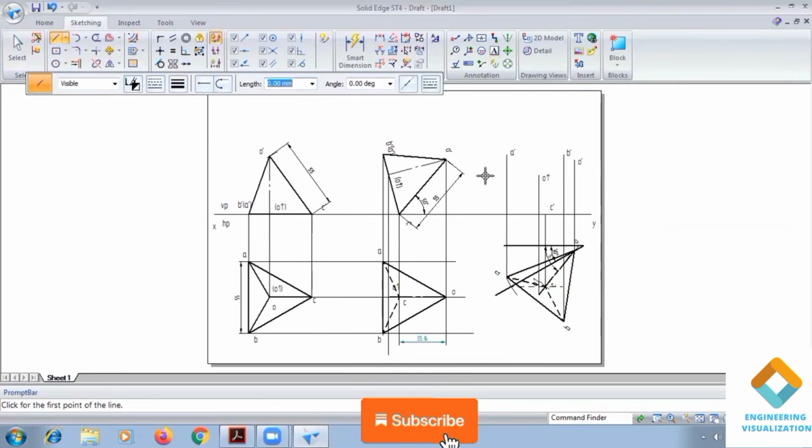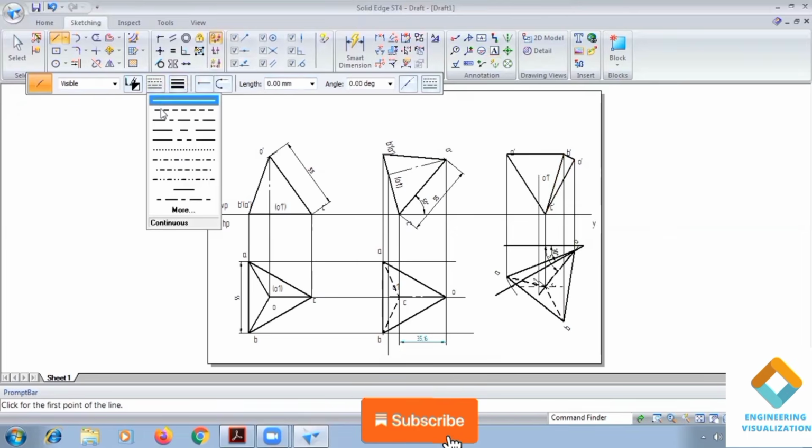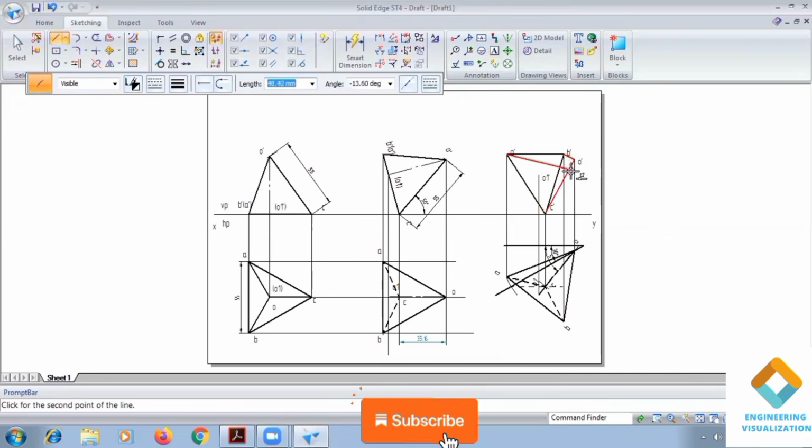Okay, after writing the notations, you can join it first. Join the triangular face and then the slant edges. If any of the slant edges pass inside, that will be a dashed line. Passing outside means it is a continuous one. So the dashed line is from this end to here. Okay, and then finally we need to draw an axis. Okay, that completes the problem.